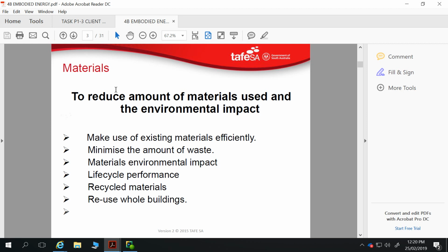The reason plasterboard comes in those dimensions is because of brickwork, the size of our bricks: 230, 76, 110. When you start building walls, you end up getting increments of 1200 millimetres or 600 mils going up and going out.